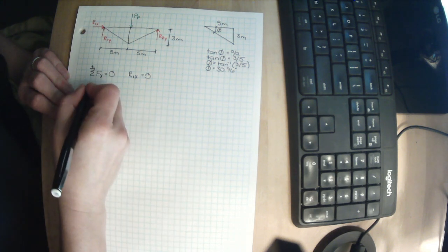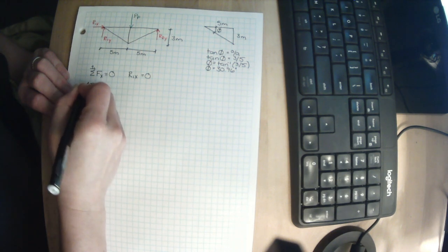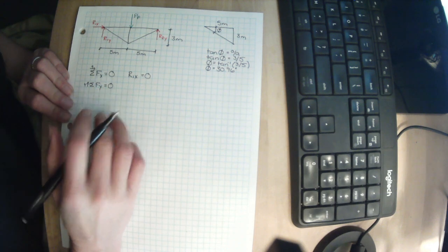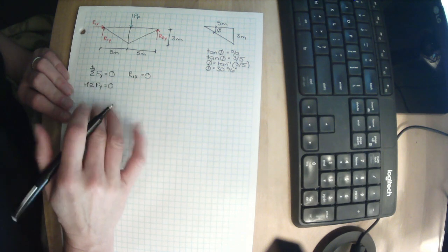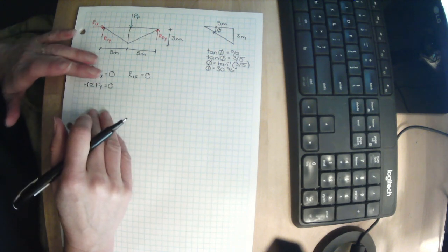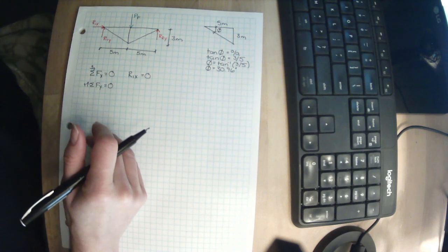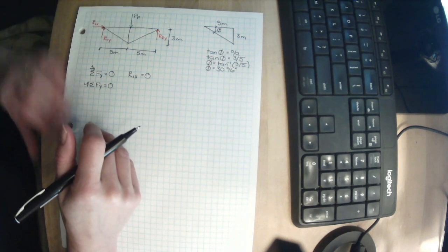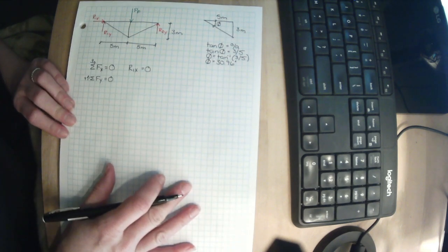Okay, let's sum all our forces in the y direction, where everything upwards is positive and the sum is 0. Now, if you remember from last year, normally I don't do this equation second. I do the moment equation. But for those of you who are new to the course or didn't do Structures 1, you'd probably find it weird that I'd go from summing the x to the moments to summing the y. That's mostly because I know the best order to solve these, but it doesn't matter what order I solve these. It makes a tiny little bit more work. So I'm just going to do it in the order that visually seems to make sense to people, but know that you could have gone right into solving the moment first here.